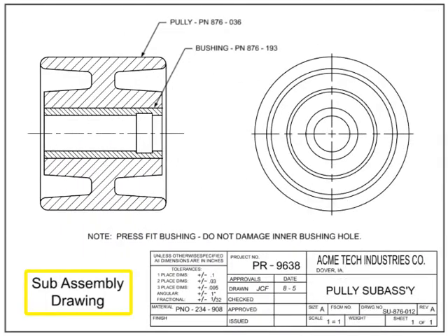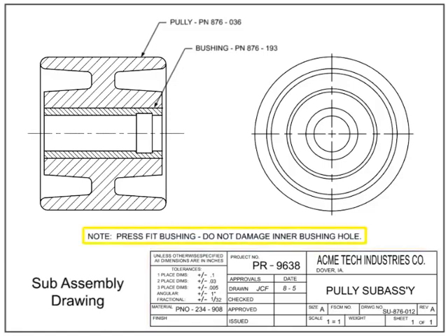Subassembly drawings are made of two or more separable items that join to form a subassembly that is then used on a higher level assembly. Subassembly drawings are useful for smaller assemblies that may go on multiple end products, such as a hydraulic valve that goes on many different tractors. One of the differences between an assembly and subassembly is that a subassembly typically has the use on or next higher assembly called out either in the title block or in the notes section.